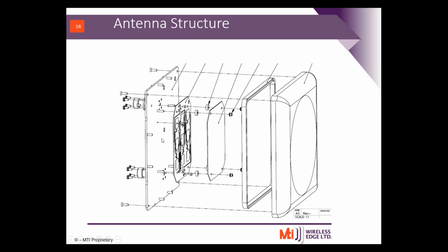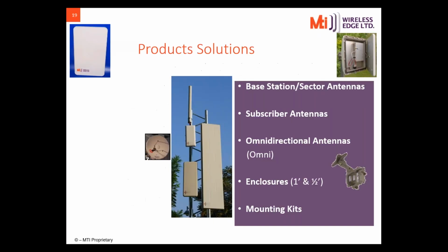Of course, everything needs to be accurate: the height of the PCB from the ground, this is the ground aluminum, and the height from the radome. This is the reason you can see spacers and everything. So everything is done by simulation and testing in the lab in order to get the best performance. In general, developing a new antenna is a process of between 3 months and 10 months, depending on the complexity. So this is the development until we give the customer the final product.